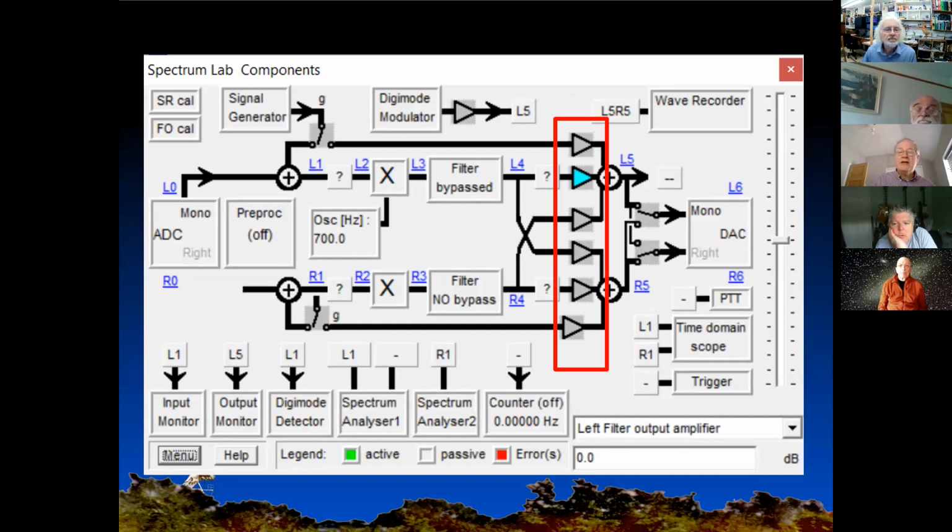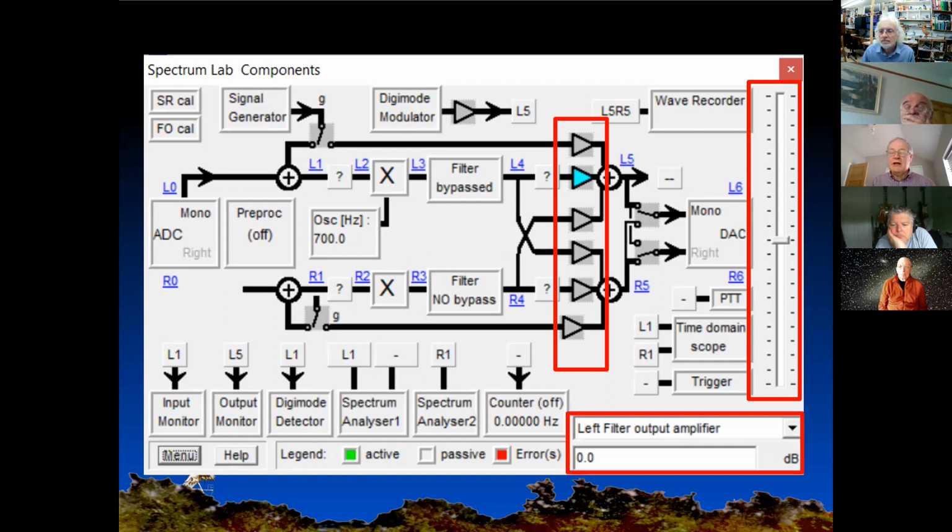There are amplification or gain control units on each channel so that you can select the levels prior to mixing. The gain is selected by this slider control on the right-hand side. In turn, what the slider control is driving is selected with these blocks down here. So you go into this pull down list, which has literally 100 or so different sources.